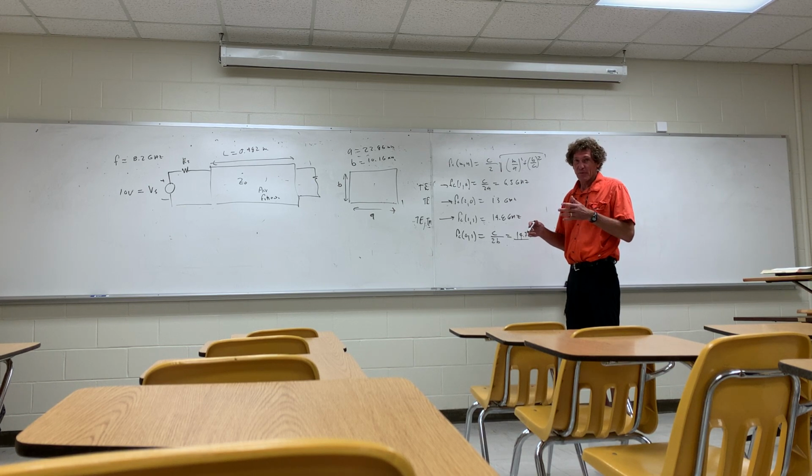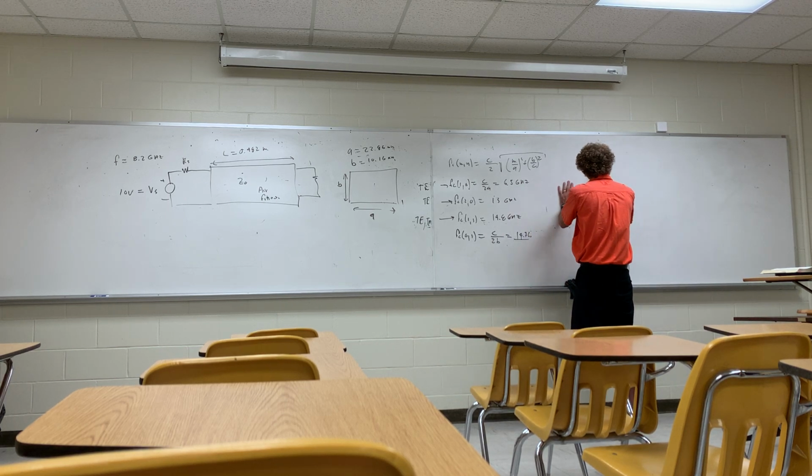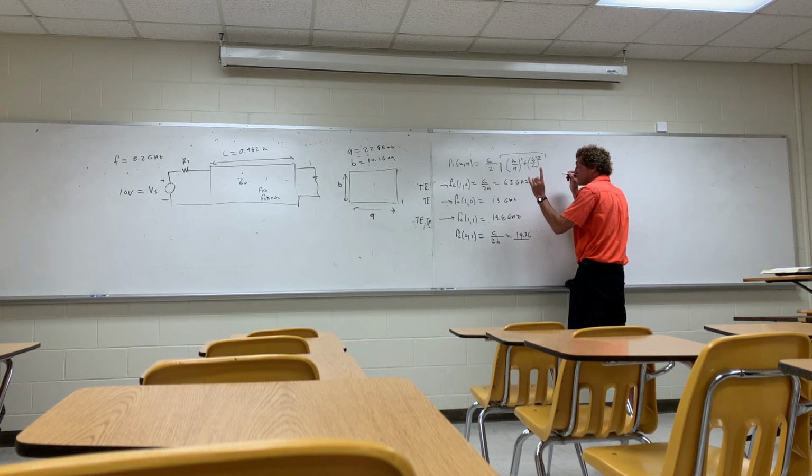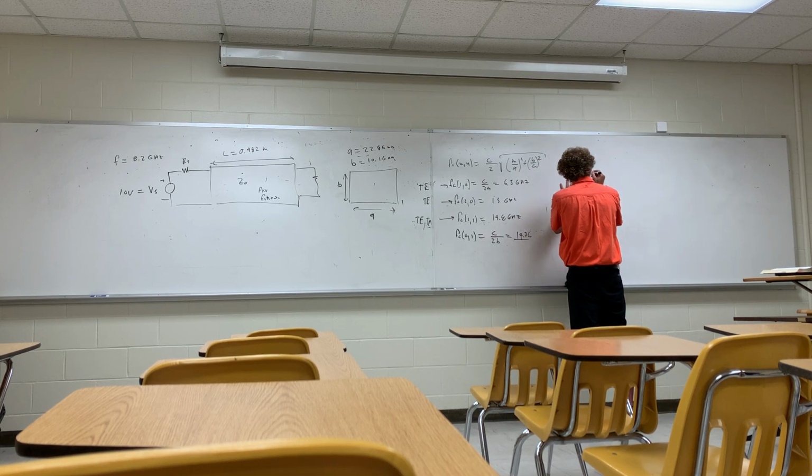Now, we know there's only one mode that's gonna propagate. Do y'all agree with this? And that's the TE10 mode. So now I've gotta get the characteristic impedance. Thank you for letting me know, Bobby, to always check the 10 mode.